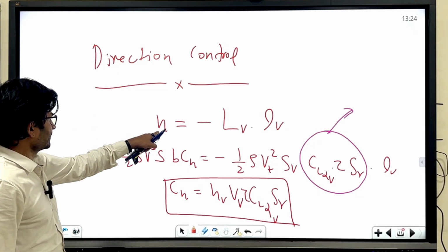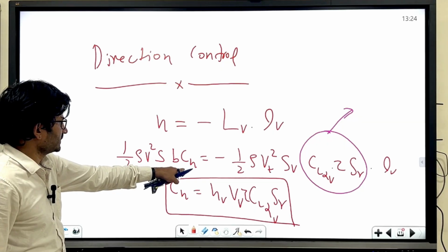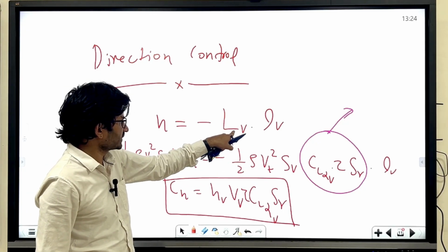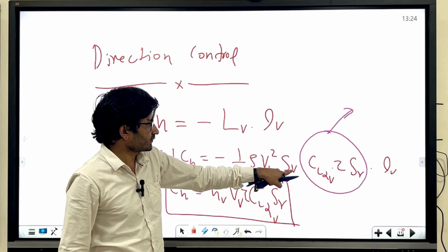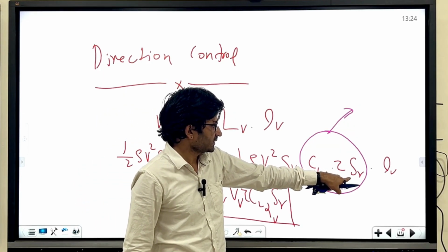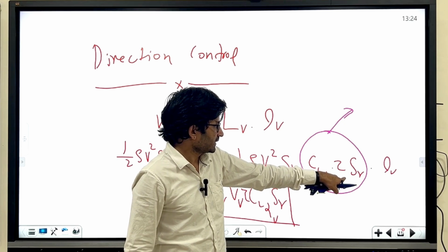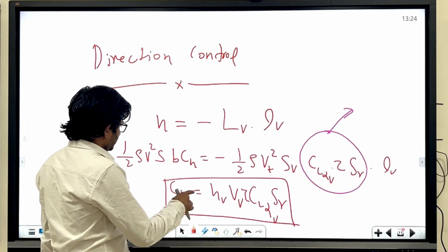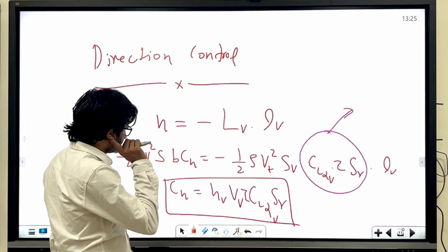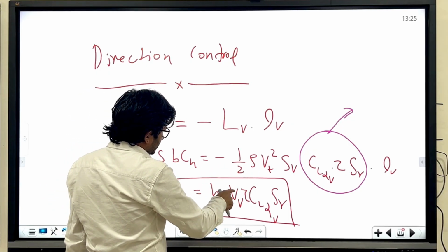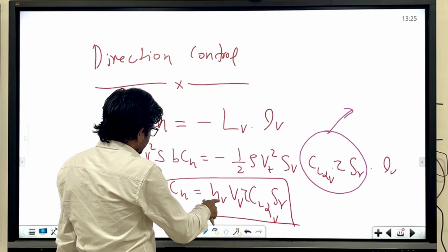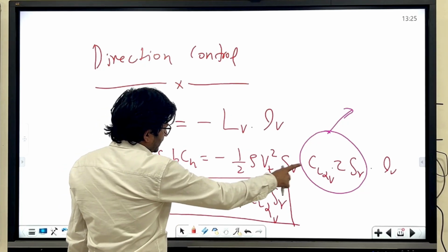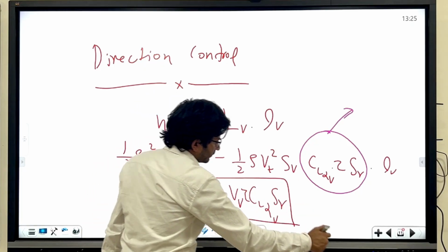I have written the yawing moment as half rho V square S b into Cn, where Cn is the yawing moment coefficient, and then minus half rho V_t square S_V l_V, with the lift coefficient written in terms of control surface deflection. I have divided by half rho V square, so half rho V_t square divided by half rho V square gives eta V, and S_V l_V divided by S b is V_V, times tau C_L alpha of the vertical tail times delta R. Fine.